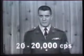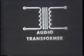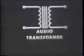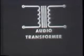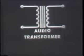Now, unlike a power transformer, which is designed to operate at a specific frequency, the audio transformer is designed to operate over the entire range of audio frequencies, which is generally considered to be from 20 to 20,000 cycles per second. The schematic symbol for the audio transformer resembles that of the power transformer. The audio transformer, however, usually has only one secondary winding. Like the power transformer, the audio transformer, too, is usually constructed with an iron core.